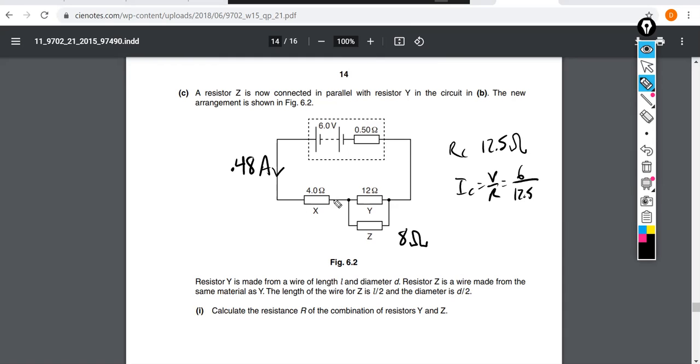So we can calculate the power developed in this resistor because all 0.48 amps are going to go through this. Here is where they'll diverge. So we shouldn't use I squared R anymore over here unless we're going to calculate how much I is going this way, this way. We can do a calculation right here though to say, what's the voltage drop across this one?